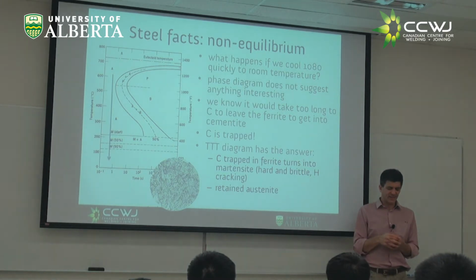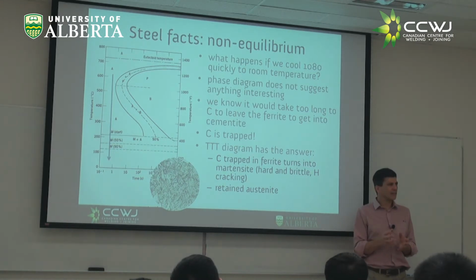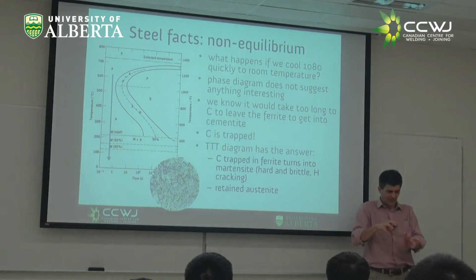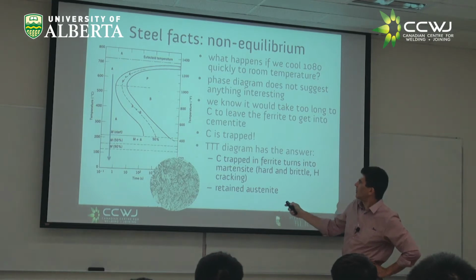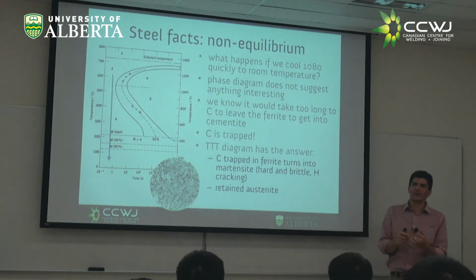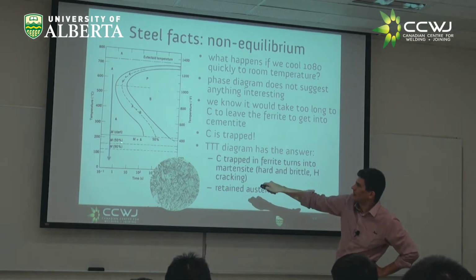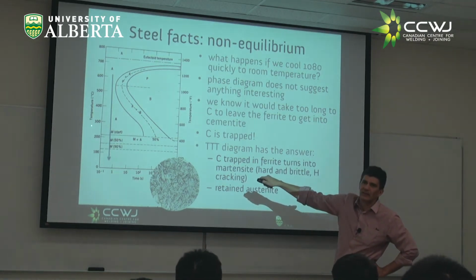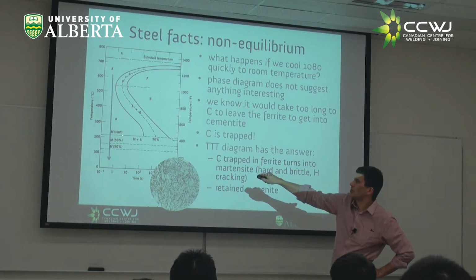And then in the case of these martensites with relatively high carbon, you turn into a BCT, right? It's not BCC anymore, it's a BCT, body center tetragonal. So the carbon happens like by distorting the lattice. And martensite is very hard, it's very brittle, right? Has all the carbides in solution. And there's a temperature at which that can happen, and this is the MS. MS is a temperature at which martensite starts.